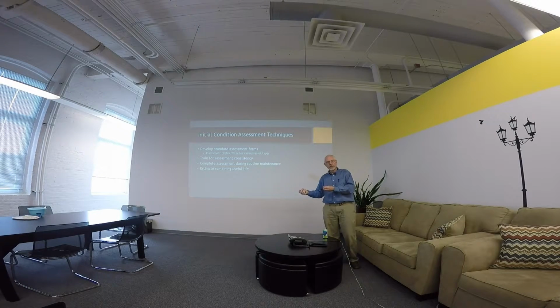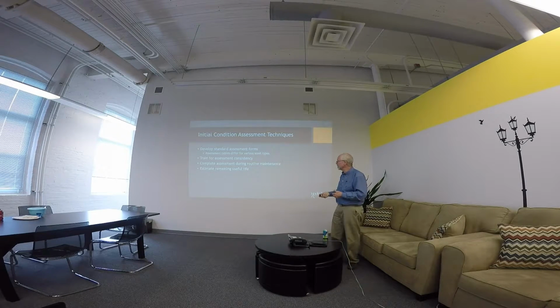So the question was, whenever they had a break, we would say, take a sample of the bedding and send it up for sieve analysis. So if they have 24 breaks a year, they'll send out 24 samples for sieve analysis and start seeing what kind of bedding they have under their pipe throughout certain areas of their system. So now they're starting to standardize their data collection.